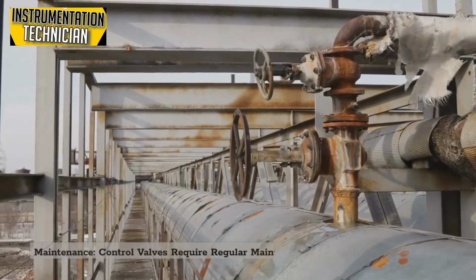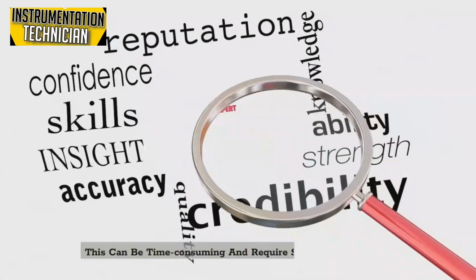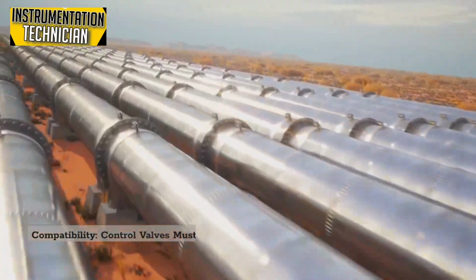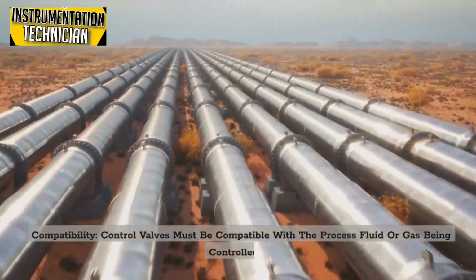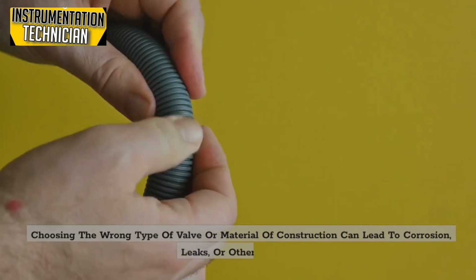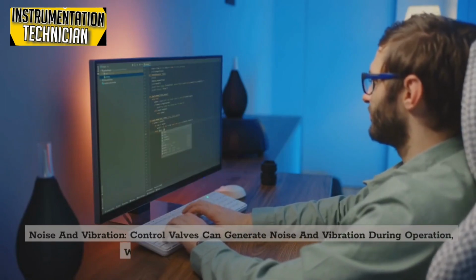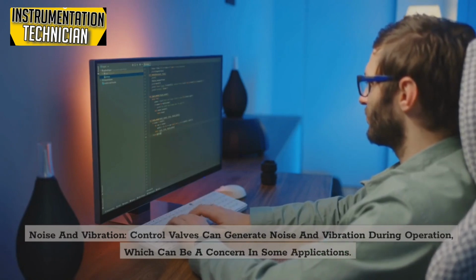Maintenance. Control valves require regular maintenance to ensure proper operation. This can be time-consuming and require specialized expertise. Compatibility. Control valves must be compatible with the process fluid or gas being controlled. Choosing the wrong type of valve or material of construction can lead to corrosion, leaks, or other issues. Noise and vibration. Control valves can generate noise and vibration during operation, which can be a concern in some applications.